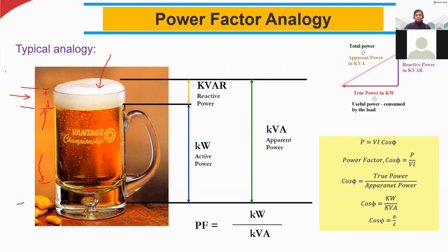So what is the efficiency? You are applying 100 watts and using only 80 watts, and the 20 watts got wasted because of the reactance. This energy loss must be reduced. That is our goal. So in industry, we use something called power factor to address this problem.